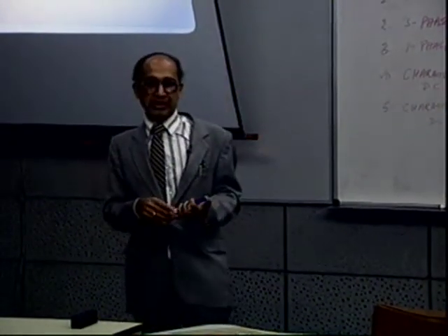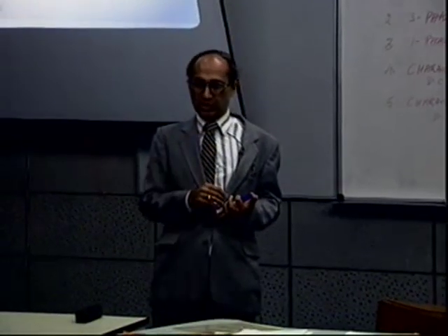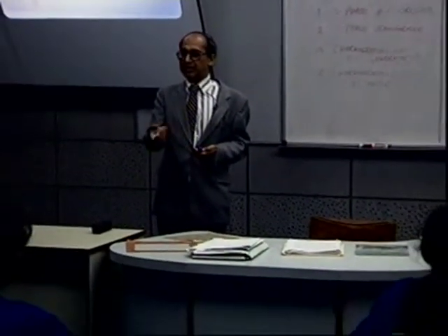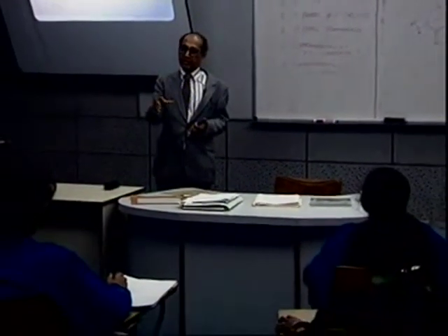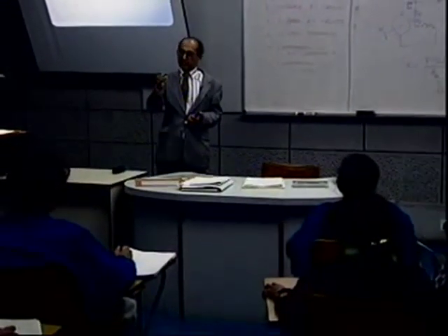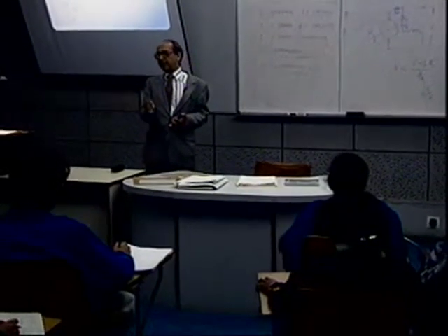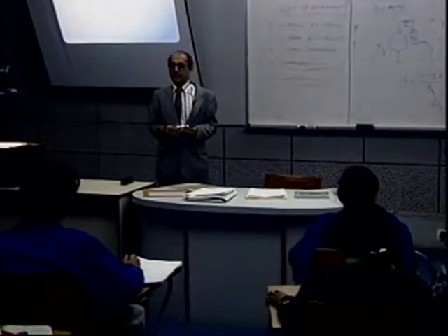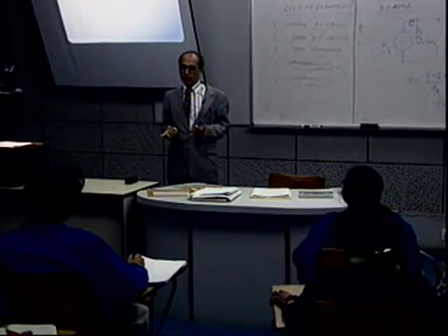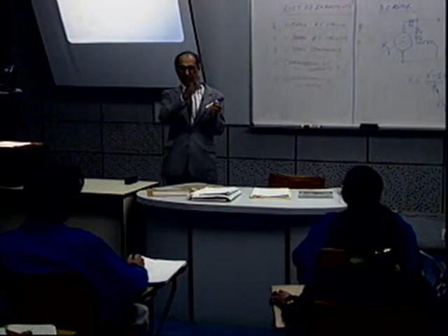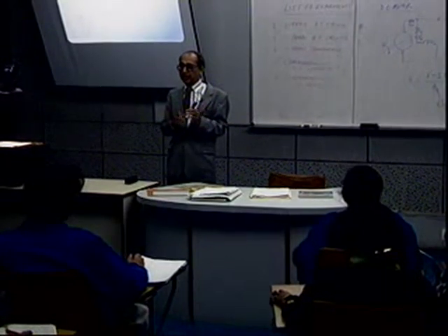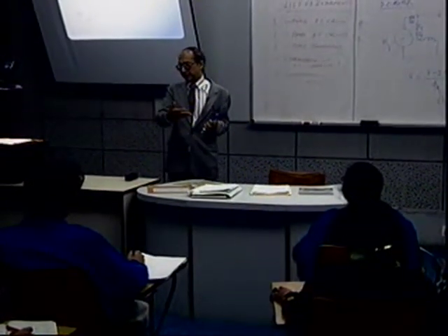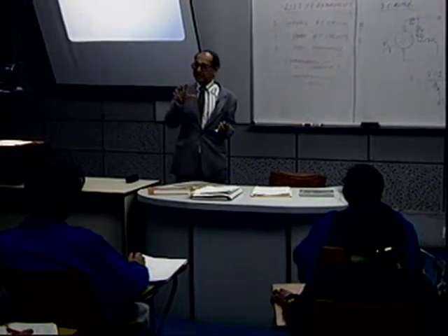Any motor has a certain rating. It operates at 220 volts. That is the rated voltage because it is designed according to that. It is designed to take that voltage; insulation, magnetic circuits, everything is designed accordingly. For a conductor, you say it is rated for 10 ampere. That means at 10 ampere, all the copper is optimally utilized. If you put 1 ampere, it is underutilized. If you put 20 amps, it will get overheated. So for everything there is a rating.